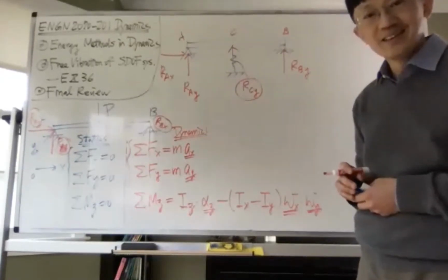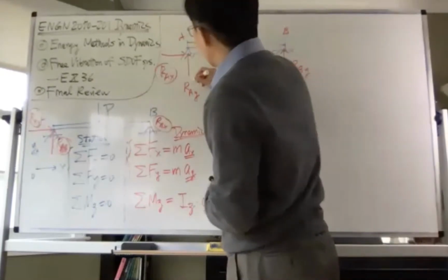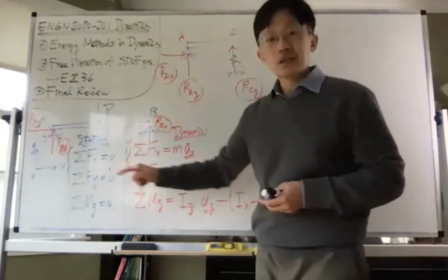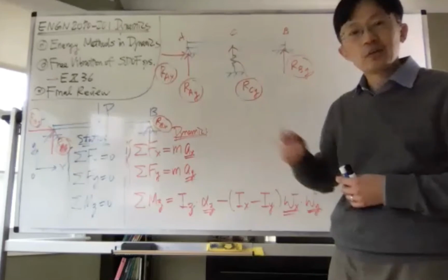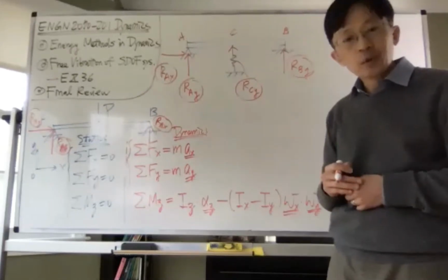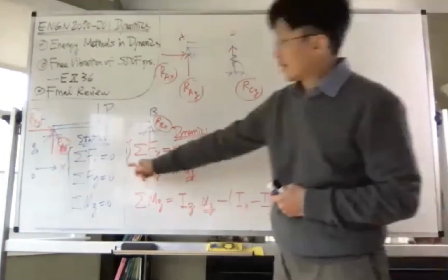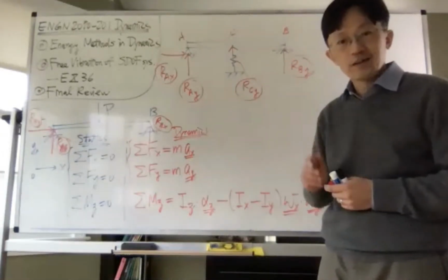Right? So here, in this kind of problem, you have 4 unknowns, but the conditions that you have from force equilibrium are still 3. This is what we call indeterminate structures. The number of unknowns is greater than the number of conditions. Unfortunately, you will always have 3 for a planar structure.